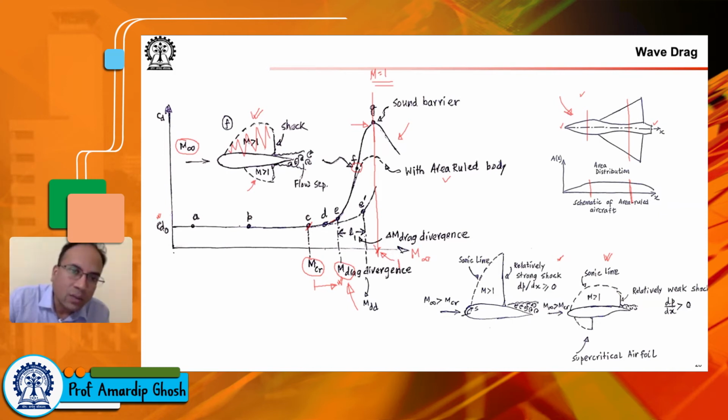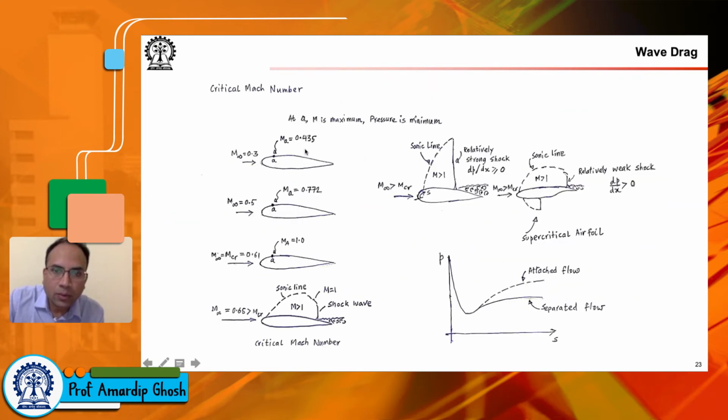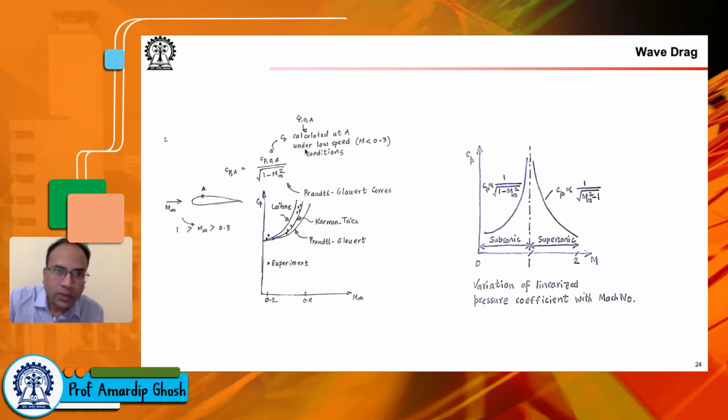You can see that these strong shock waves formed on the top and bottom create this flow separation, and create the lack of balance between forces on the wing from the front and rear, creating this large drag component. We call it wave drag, because the primary source is the shock waves impinging on the boundary layer, causing large flow separation.